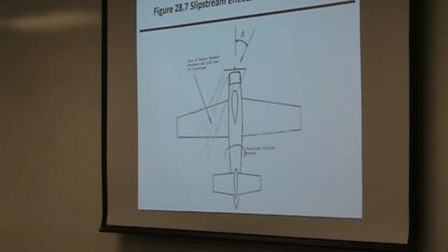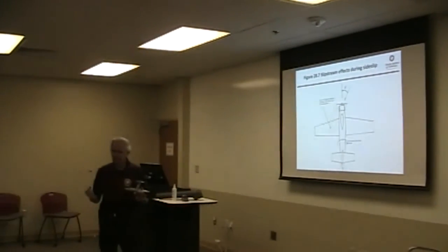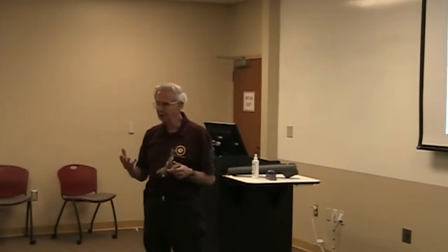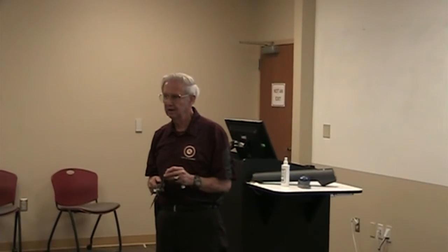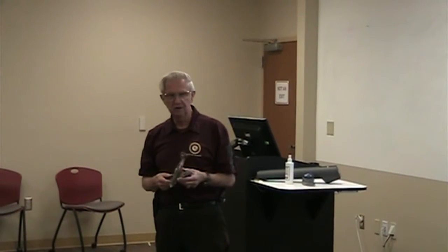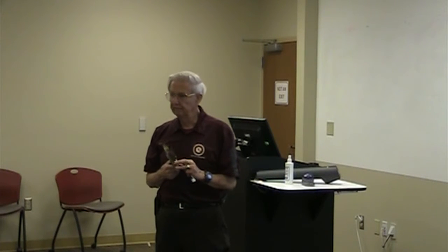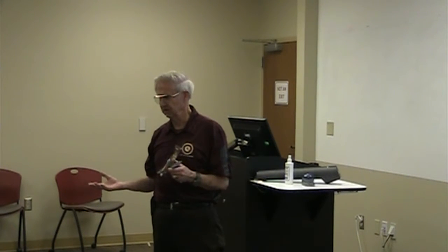We will look at this on the Cherokee 6 when we fly, and you'll see that low-wing airplanes have a hard time passing the FARs regarding lateral stability because of that. Because you can get to essentially a full rudder side slip, and for a steady heading, you may not have more than 5 degrees of bank, and the rule says you should have 10. Well, 10 was based on Cessnas. High-wing airplanes will have it.